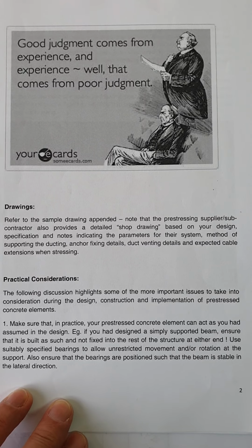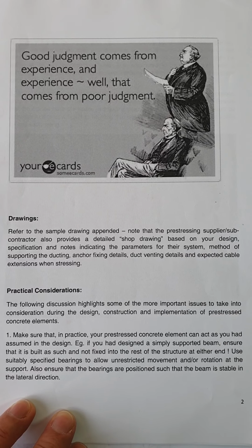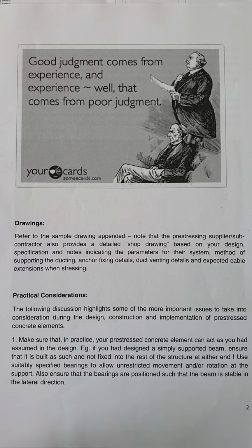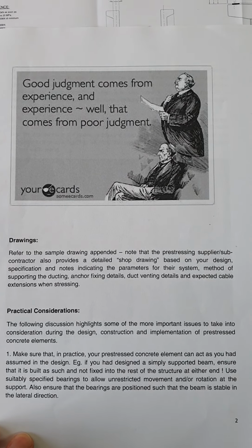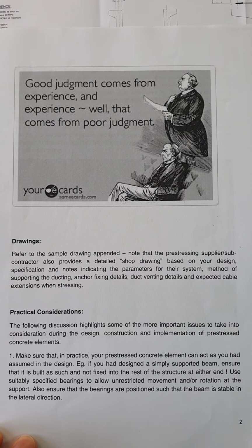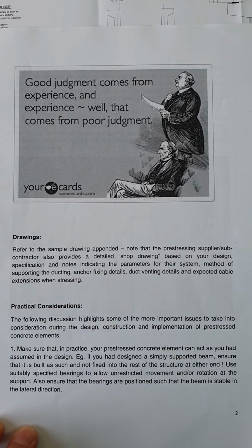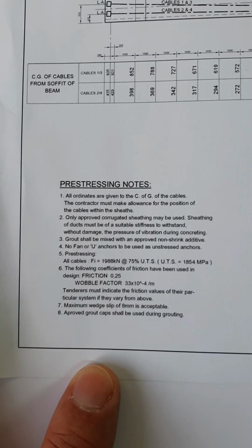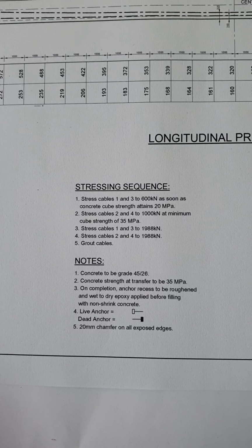So that sample drawing that I put onto the Moodle site, download it, have a look at it. Just bear in mind that that's some pretty basic information that we put on this drawing. Once this has gone to the contractor, he will send it off to his pre-stressing subcontractor, and then they provide a very detailed shop drawing based on the information you give them. Probably one of the most important things is that you get the pre-stressing notes right, and any stressing sequence or any other notes that you put into the drawing.